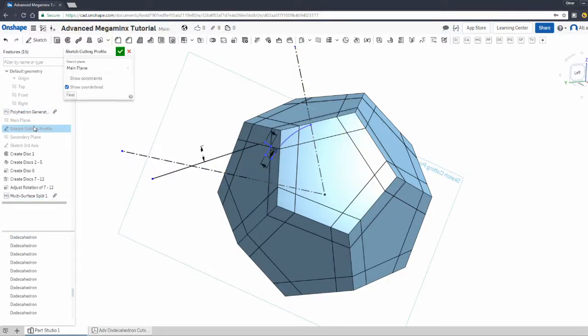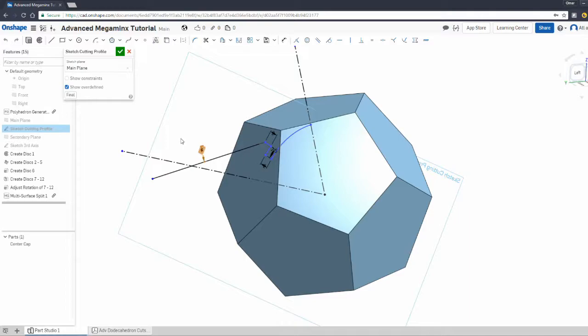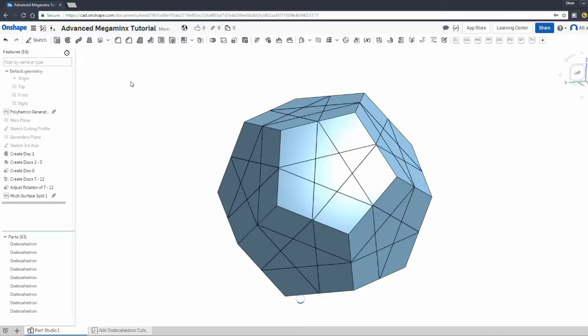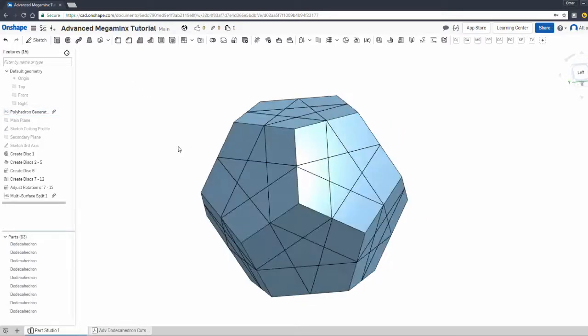What that means is if I go in the other direction, my centers should get smaller. So let me crank this up. We were at 7, right? So let me make it 8, for example. And now you'll see we traveled further along the face, the side of the dodecahedron here. And when I click OK, you will see that my centers will get smaller, and my edges will get smaller, and my corners will get much larger, sort of the negative effect.